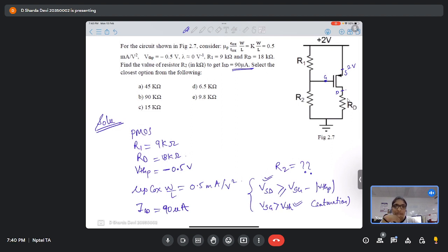Do you know the potential over here? No current will flow in. But for finding VGS, or let's say VSG, what does it actually mean? It means Vs minus Vg, right? So we need to know this Vg, the potential at this point. Do you know it? No, right now we don't know. So can we guess the region of operation for this transistor?